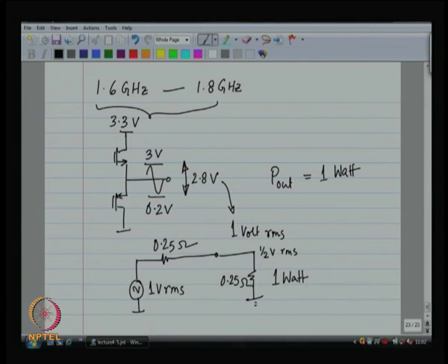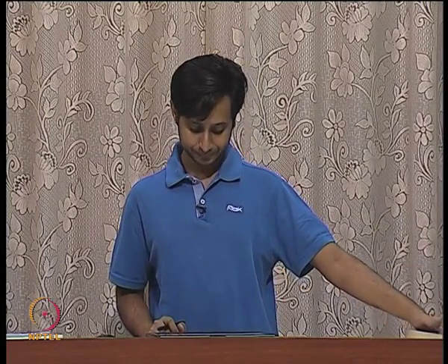Okay, so, this is the case where you get maximum power transfer. To reduce the source resistance further, indeed you can get even more power out, but it is not advisable, because reducing the source resistance further and further is just going to blow up the size of the power amplifier. All right.